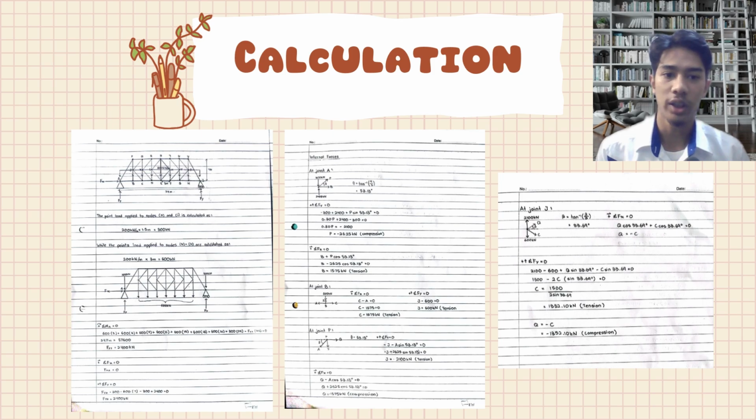Taking the moment about point A, we sum the moment of all point loads and set them equal to the reaction at Fy2 times the distance of 24 meter. Solving for Fy2, we get Fy2 equals 2400 kN. Using total Fy equal to 0, the vertical reaction at Fy1 is also calculated to be 2400 kN. There is no horizontal force, so Fx equal to 0.